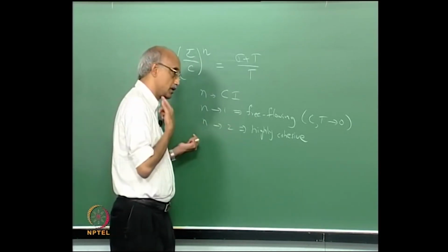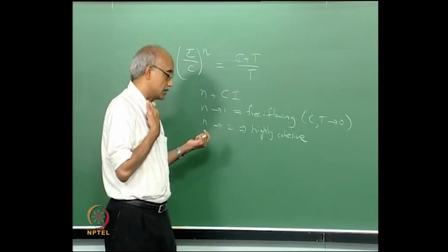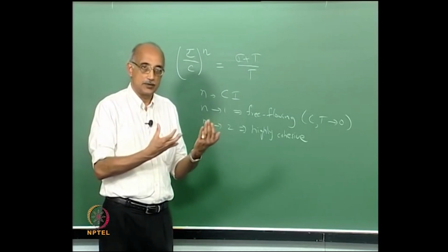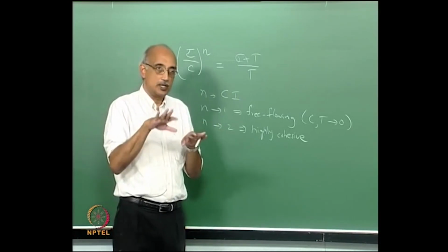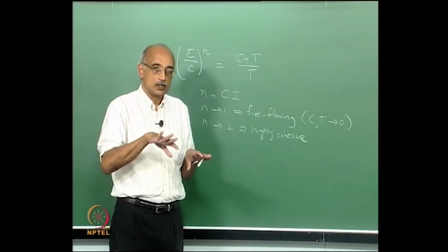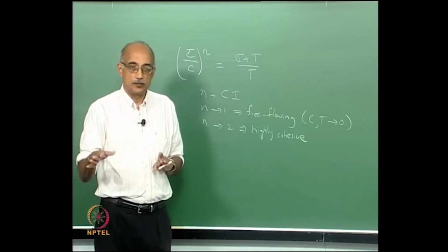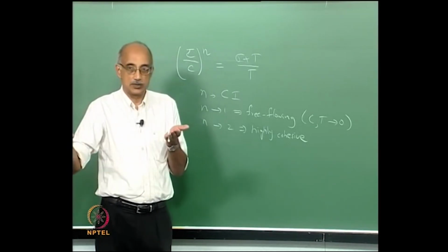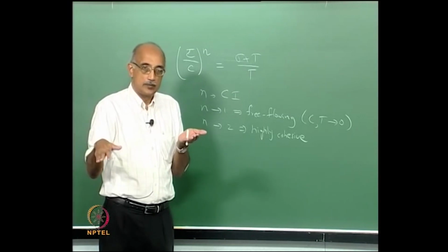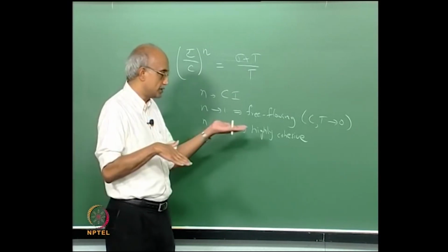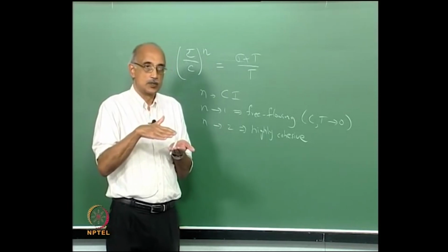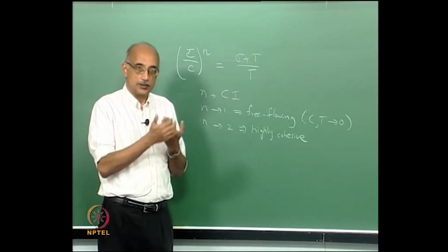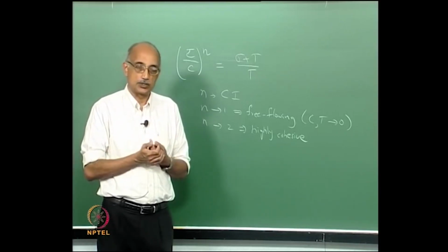The cohesiveness has a bearing on essentially the correlation of motion between adjacent grains. So the more cohesive the material that's stored, the more correlation there will be between the motion of adjacent layers. So as soon as you start the flow from a silo, as soon as one layer moves, the other layer will also start moving in the same fashion because it's correlated. Cohesiveness also affects the friction between layers. The more cohesive the material, the less friction there is between the layers, and the smoother will be the flow that is induced.